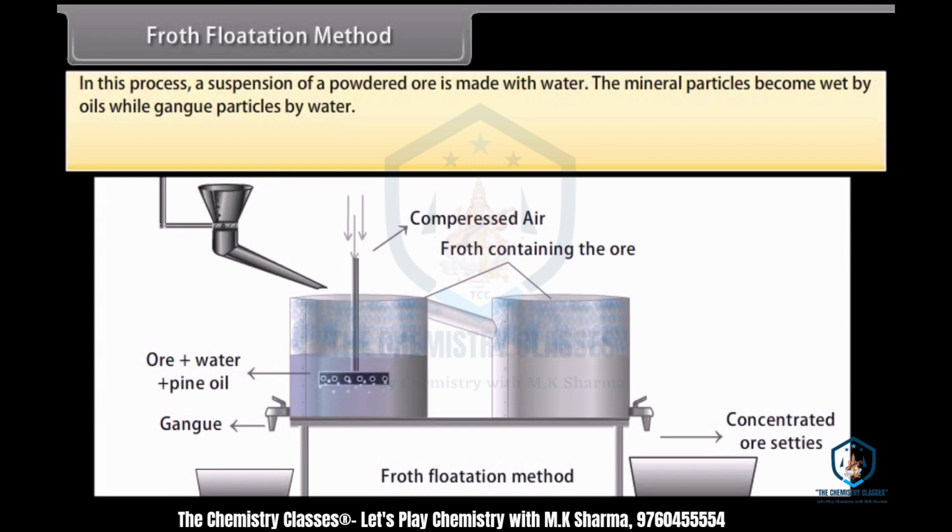Collectors like pine oil, fatty acids, and xanthates are added to it. Froth stabilizers like cresols and aniline stabilize the froth. The mineral particles become wet by oils while gangue particles by water.